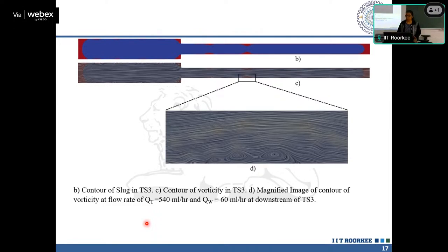If you recall the flow pattern map, we saw the formation of a long slug when they encounter the sudden contraction. But what we haven't captured through the high speed camera is the presence of such waves, that is, disturbance waves generated due to the sudden change in area from the vena contracta.